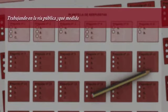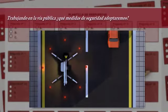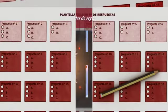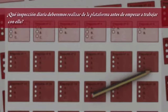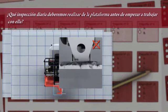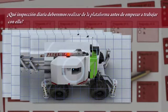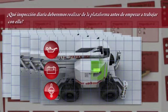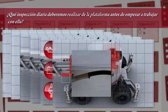Working on the public road, what safety measures will we take? To surround the working area with cones and visual signals, and to connect the rotating light. What daily inspection do we have to carry out with the platform before starting to work with it? Inspect the weld and the structure. Avoid all types of grease at the access to the platform. Check the brakes. Check the good condition of lights and signals, oil, battery water, and the joints of the machine in order to observe the possibility of hydraulic oil dripping.